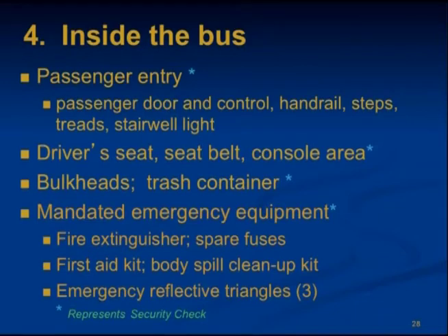Make sure that the handrail is secure, steps are not obstructed, and the treads are secure. Make sure the stairwell light is not broken. Make sure there's nothing out of the ordinary found in the driver's seat area or console area. The driver's seat belt is intact, not frayed or cut, and operates smoothly.